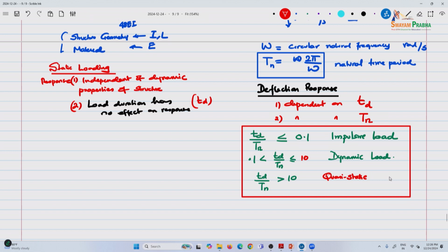UT machine. In natural phenomenon, buildings, any examples of quasi-static? Wind, right? Wind load. Yeah. So, wind, even if you see seismic, right, that goes into minutes. Your natural frequency, your time period is certainly not in minutes, even for buildings. So, what we see on the left hand side is quasi-static, and these are some concepts that we will be exploring in the coming days.